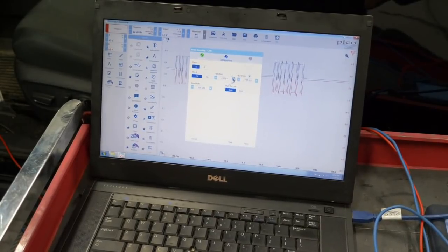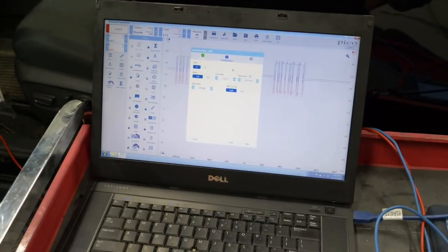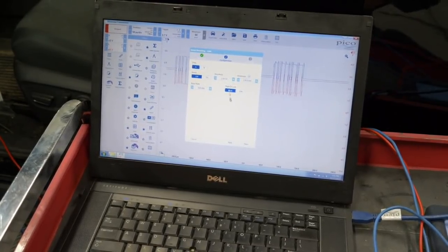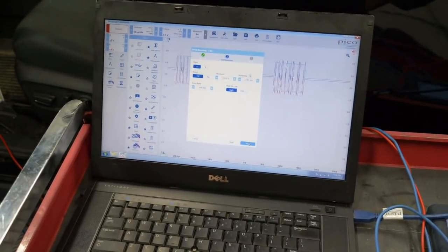And now when I did that, it brought up some other criteria to set. Yeah, I would leave those the same because the protocol does specify the sort of voltages that you should expect, and you should always be getting those. If you had to adjust these, it would be because you're actively troubleshooting a problem, because it should fall within that range. Yeah, I understand what this is now, because this is my threshold voltage up here on my channel A. That actually makes total sense to me now.